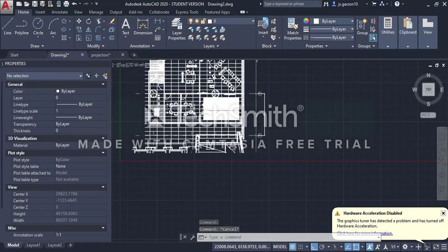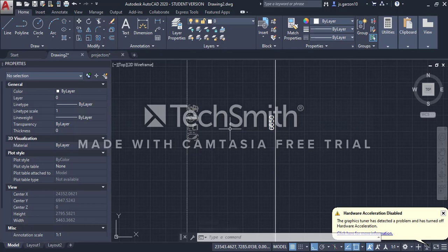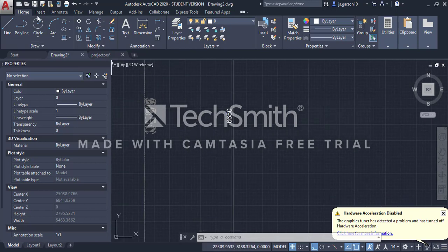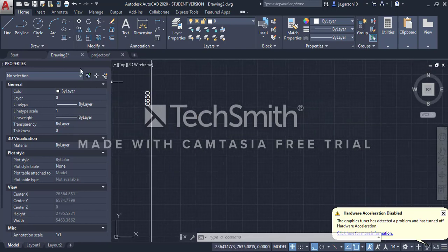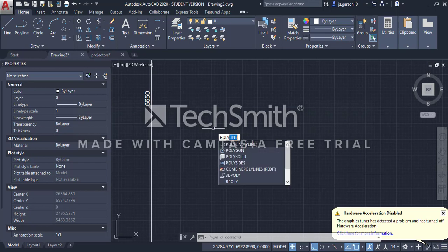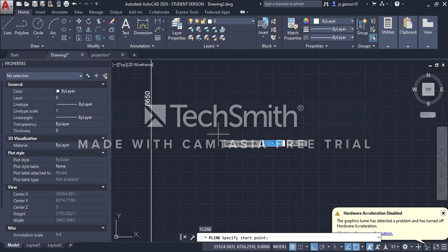As you remember, I typed scale as a command. This is the command bar. I can also do this with other options like polylines or lines, because it will be much quicker than searching for those tools in the taskbar. So for polyline, I can just simply type polyline and it will automatically appear. So you can just select it like this or press enter.